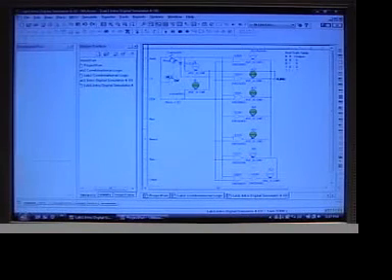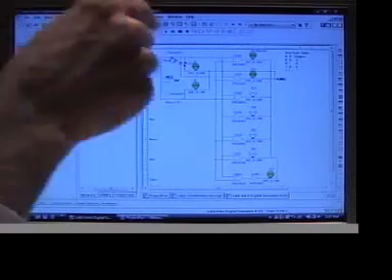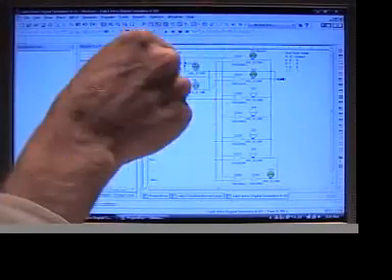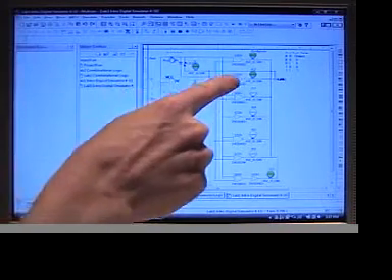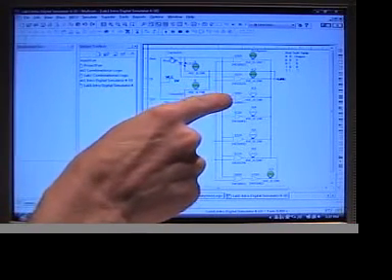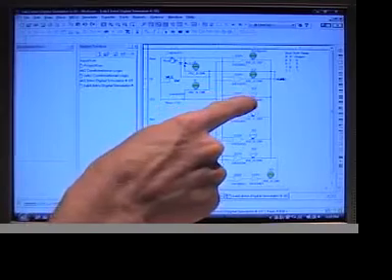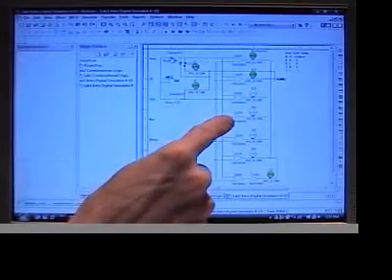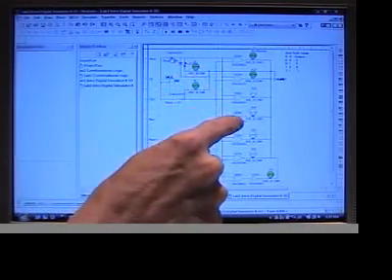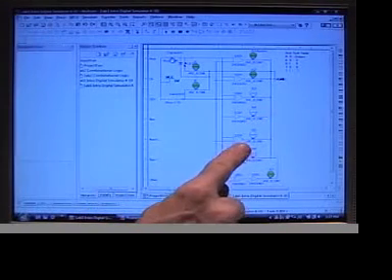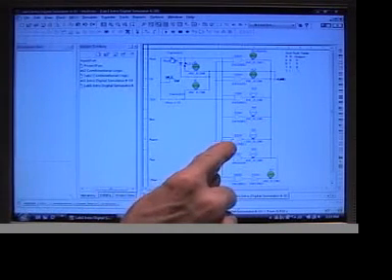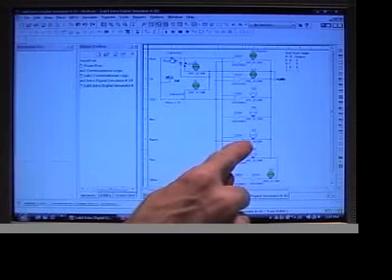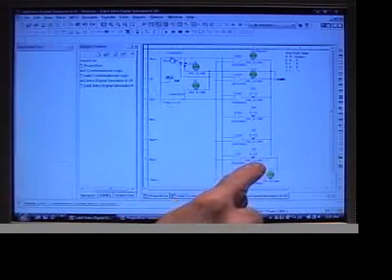If I close both input switches, you can see the pattern changes. Now the AND gate has a 1 in the output. The OR gate still has a 1 in the output. The exclusive OR gate has a 0 in the output. The inverter now has a 1 on the input, and so a 0 on the output. The NAND gate has two highs, two 1s on the inputs, so the output is a 0. The light bulb is not lit.